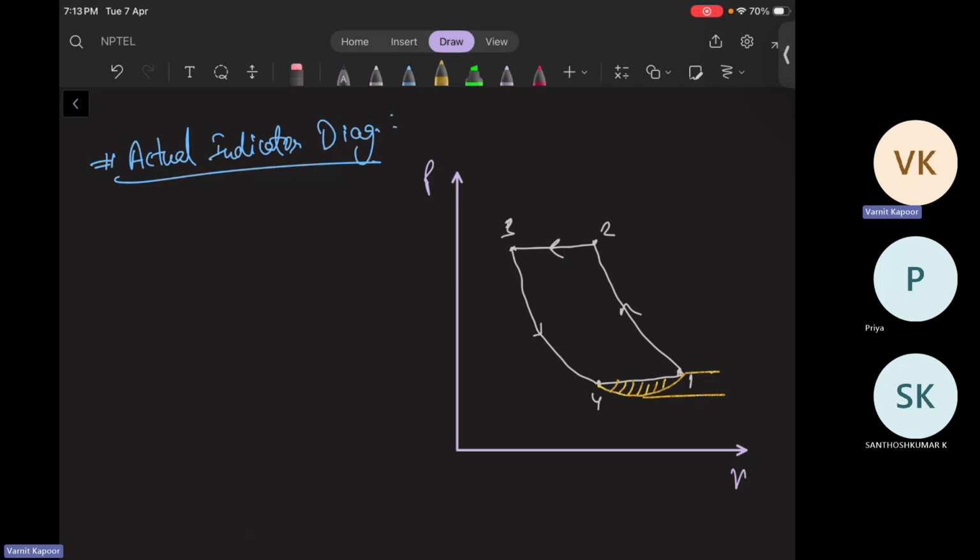This is your change in pressure difference in suction, delta P S. And similarly, when you are delivering out of the compressor, that means your pressure inside the cylinder must be higher compared to the ambient. Because of that pressure difference, you will be able to deliver outside. So this is your pressure in delivery, delta P D. Okay. More pressure required to discharge and lesser pressure required for suction.